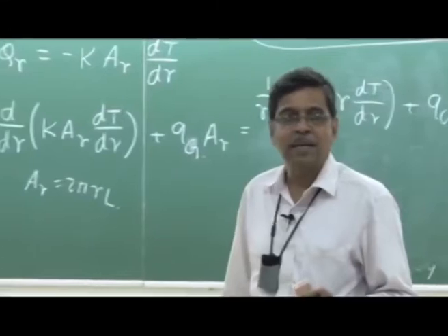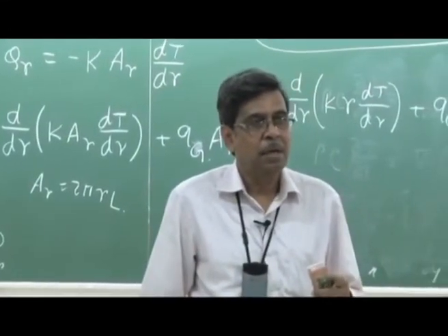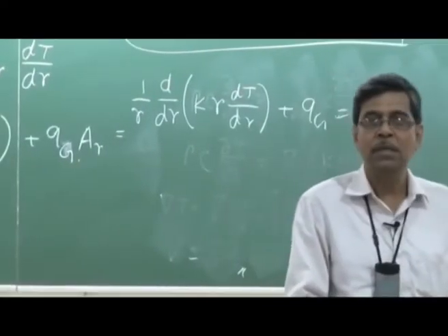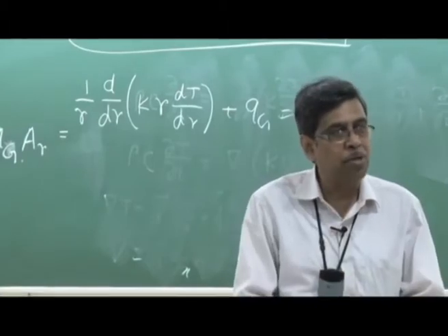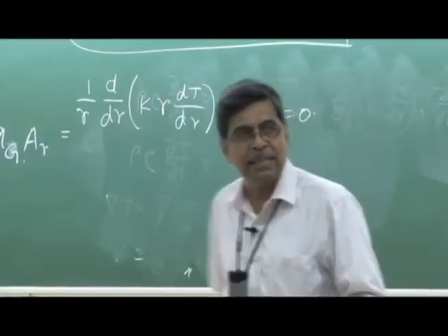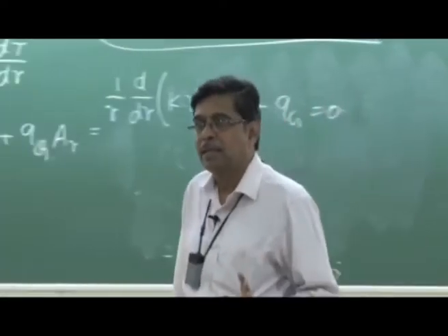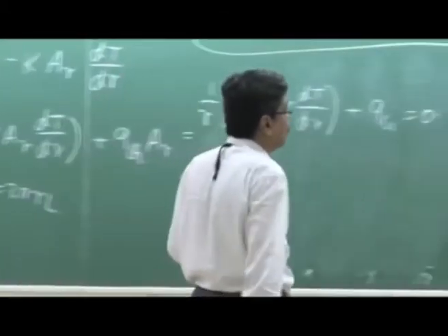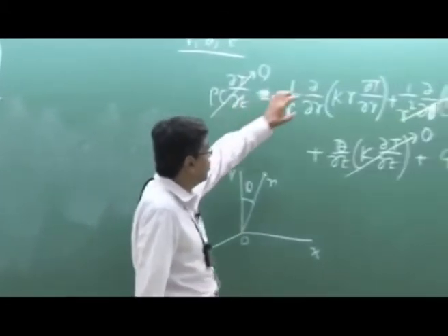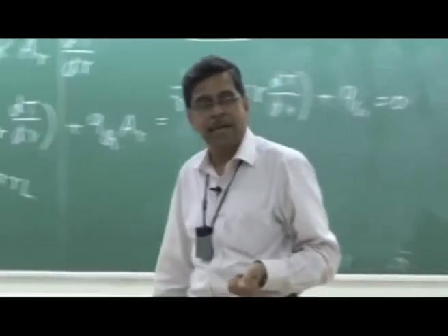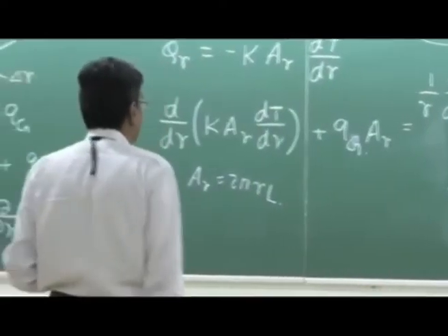And then recognizing the heat flux flowing across each plane, take a balance of the total heat flux coming into the control volume with its change in energy, the way it has been done for Cartesian coordinate system. And it is a routine matter, and it is done in any book. You can see that this is not being done in the class, but the easiest way is to convert this into cylindrical polar coordinate system by expanding this divergence k grad T in the respective cylindrical coordinates.